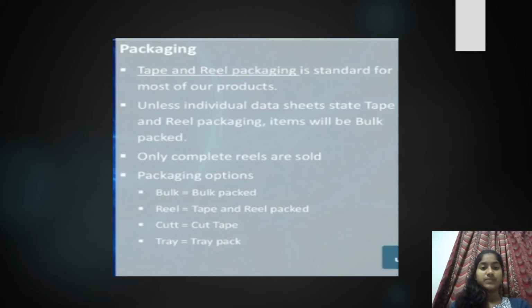Supply voltage. It is necessary to specify the supply voltage for the VCXO to ensure that it operates with the supplies available within the electronic design. Also, check the tolerance of the supply to ensure that there are no mismatches in tolerance. Often, any voltage regulator will be able to provide a tighter voltage specification than the VCXO needs, but it is always worth checking during the electronic design phase so there are no nasty surprises later.